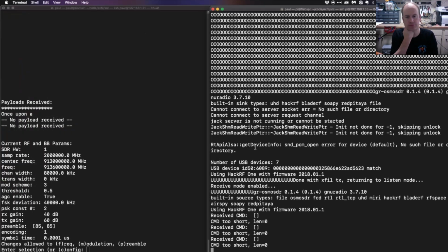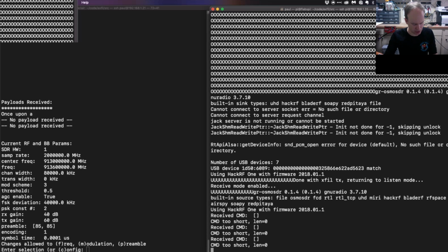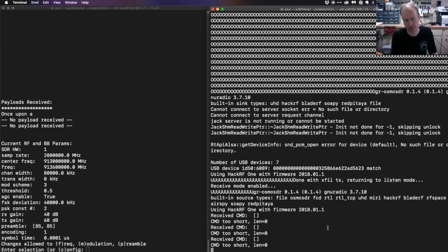And I think GNU Radio has some really cool utilities where you can see a waterfall flow graph of the different frequencies and what is being transmitted. Do you have any other ideas on what people can do to identify possible wireless signals that should be of concern? Yeah, it's tough, but definitely you can roll your own tools or just use simple flow graphs in GNU Radio, like you were saying. It takes 2 blocks strung together to create a simple, very simple spectrum analyzer.